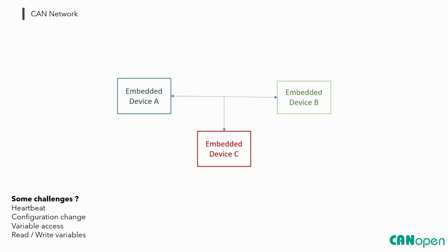It's a very basic example, and at any point any of these devices can generate a CAN packet, and the CAN physical layer will take care of the collision. Using a method called arbitration, it decides which packet should transmit first, and then immediately after that the next packet can also be transmitted. This is perfect up to this stage, but let's talk about a more complicated scenario.